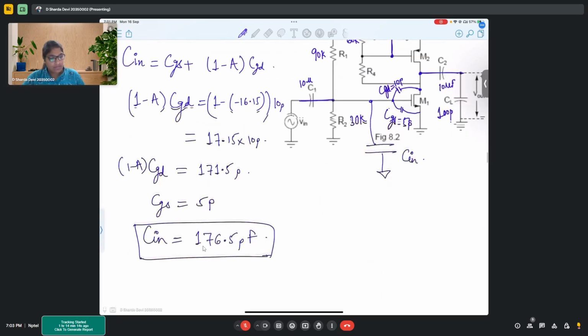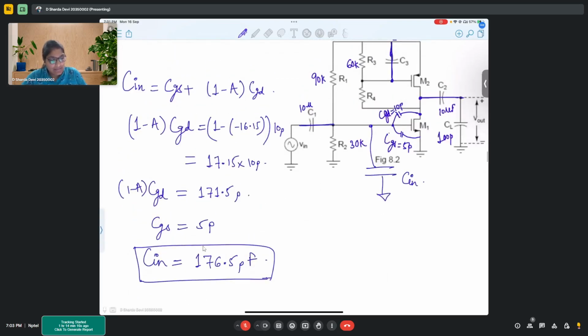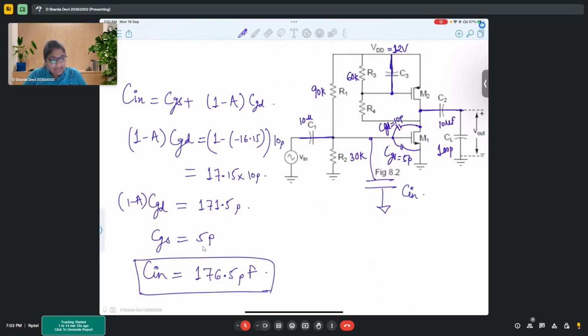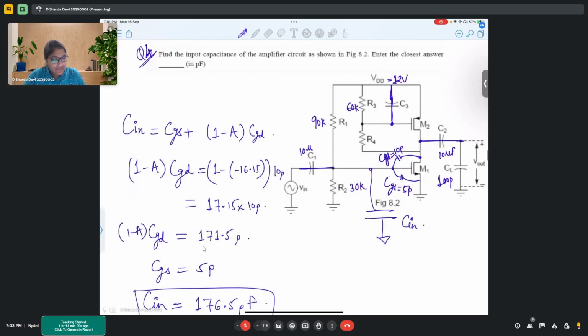So this is clear, right? Because in the circuit's gain, first of all, we have used the GM of this transistor only, and Z out will be the output terminal's resistance. In this particular Z out, you would observe the behavior because of the impedances due to the presence of both the transistors. So that's why we would directly use the gain from the whole circuit here.